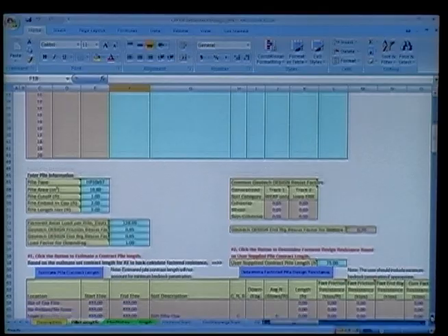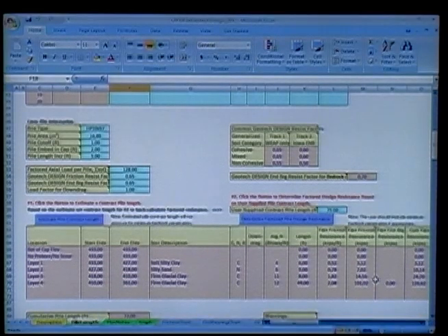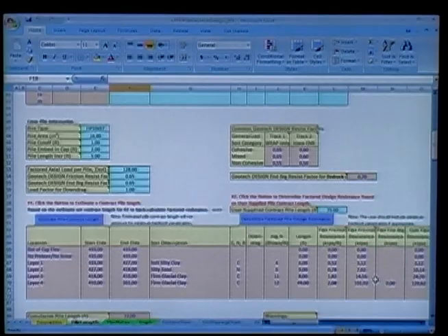I'll add this too as I go down here. Pile design in the past, we joked about a little bit at work. You always kind of do it on a napkin or the back of an envelope, right, because it was so easy. It's still pretty much that way as long as you don't deal with setup. Otherwise, the only difference really is you have a little different blue book values, a little different phi factors for mixed and non-cohesive. But if you throw setup in there, it gets a little more involved. So that's why we wrote this. We had a spreadsheet in-house for the old ASD, but I don't think anybody hardly ever used it because you just write it down quick and you'd be done. So hopefully this keeps that process a little faster.